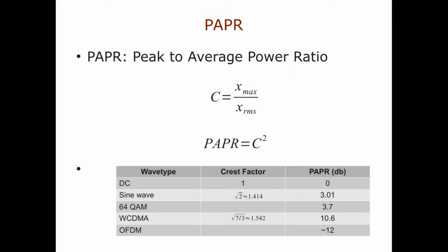And when it comes to the 4th generation OFDM, or the OFDMA as it is commonly known, the PAPR rises to about 12 dB. Now this PAPR increment with each technology is a serious issue for a designer, and hence every designer is looking to minimize the PAPR by using reduction techniques, which are commonly known as crest factor reduction.